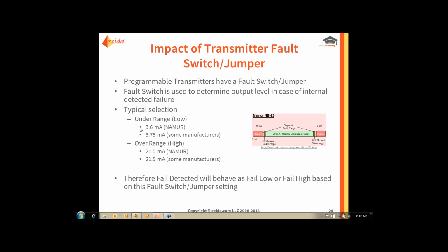If you deal with drift failures, then you may drift high, you may drift low. That would probably be the only case where you would ever see a safe failure directly assigned to a transmitter, at least done in an FMEA, because it may drift high, it may drift low. In some cases it goes to dangerous, some cases it goes to safe. But anything that is basically stuck in the healthy operating range, we tend to flag as a dangerous failure. So I think I've answered all questions.